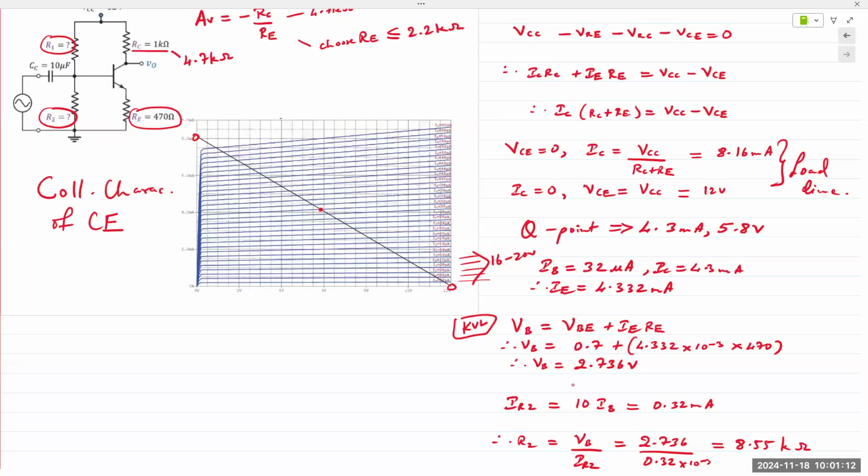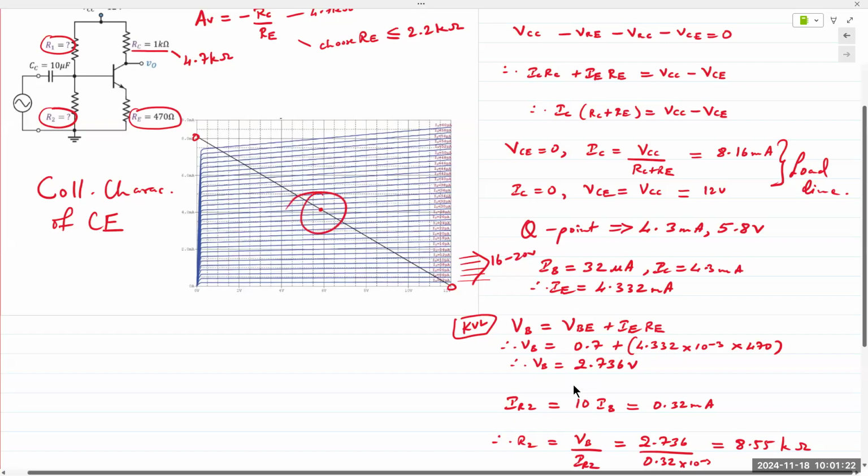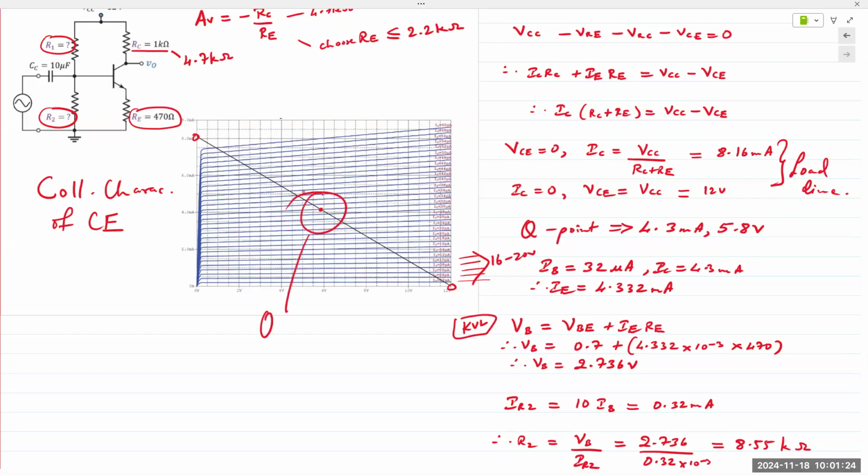And then you have your load line intersection point. That's where you determine your Q point, obtain the IB values and the IC values as a starting point from your graph, and then perform the rest of the calculation. Lab 7 data.